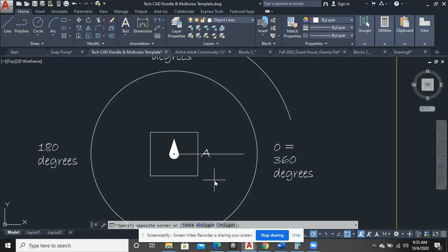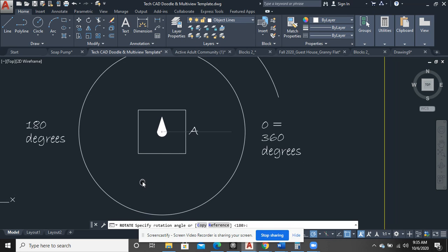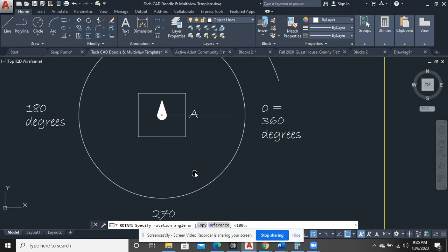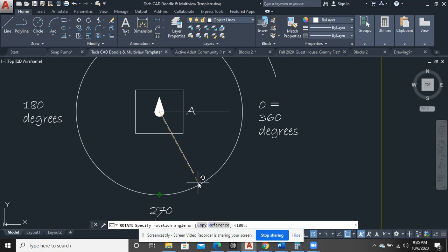So if I want this line to come 45 degrees in this direction, downward from where it's at, what you really have to do is a little math. You have to say you want to rotate it, select right here, and you can think about this however you want. I'm normally like an additive person, so I kind of come around and I say, okay, it's got to be here, which is 45 degrees behind 360, or it's 45 degrees past 270. So however you get there is fine.